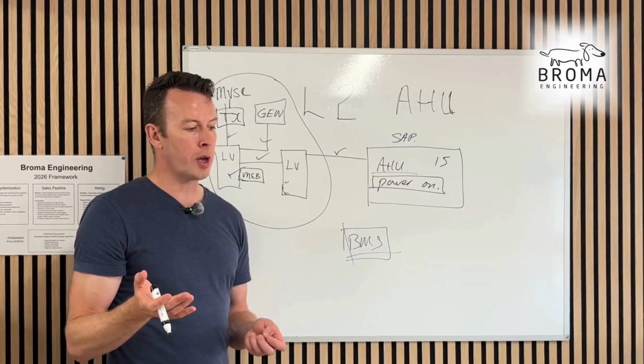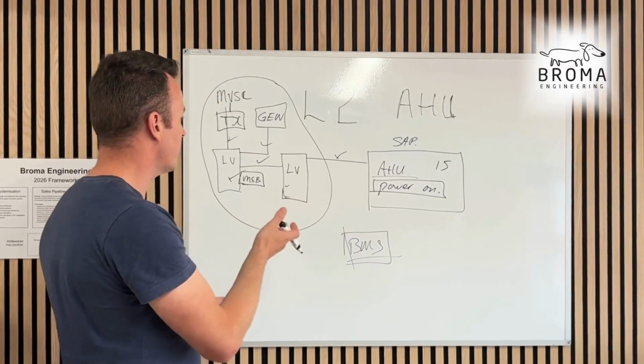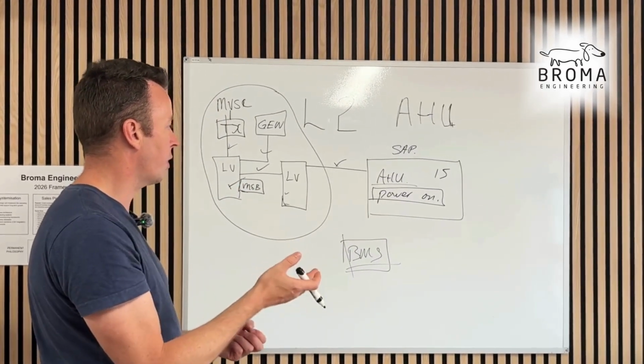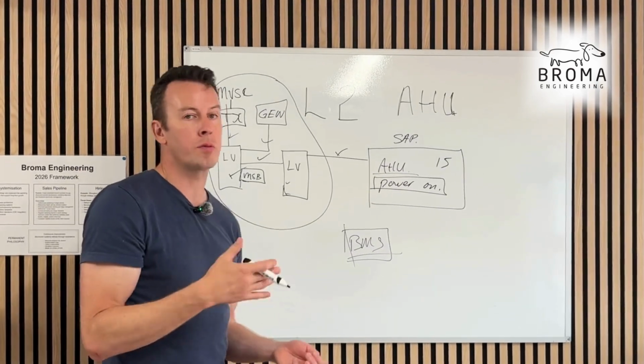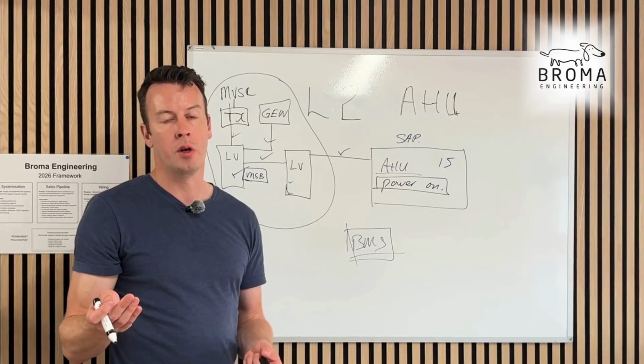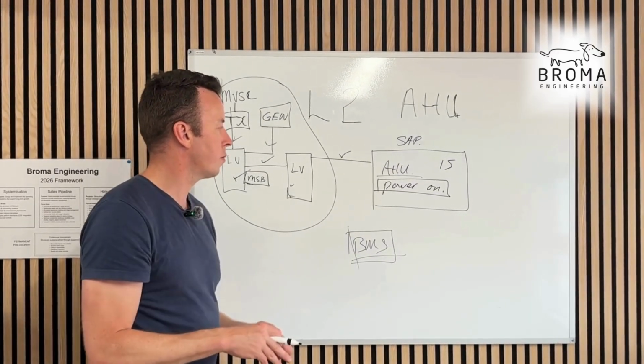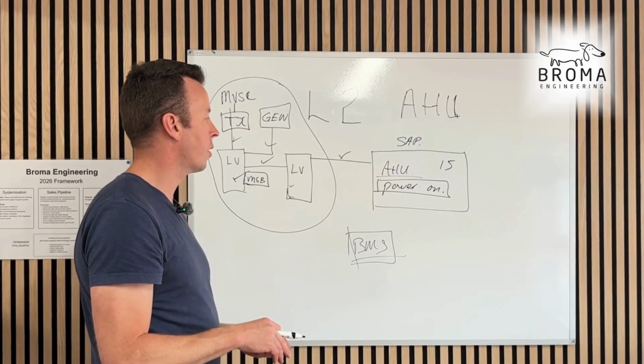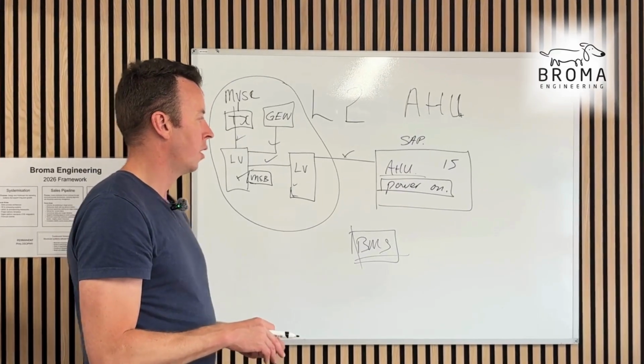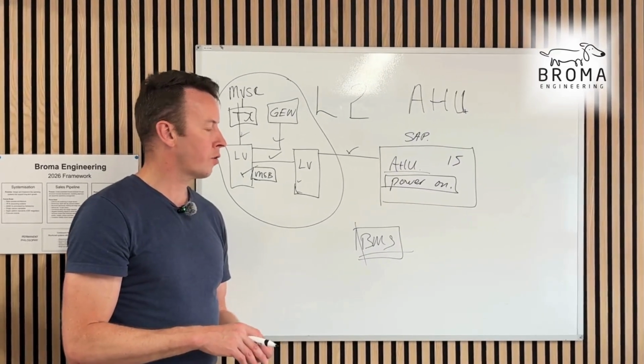It needs to be in your commissioning plan how you're going to do this as well. The sequencing, if it's dual fed: are you turning one on now, are you turning them both on? What's in the switching plan also. And everyone's involved, and we have a power on meeting the night before we do power on. We go through all the paperwork, go through all the snags, make sure there's no critical snags.